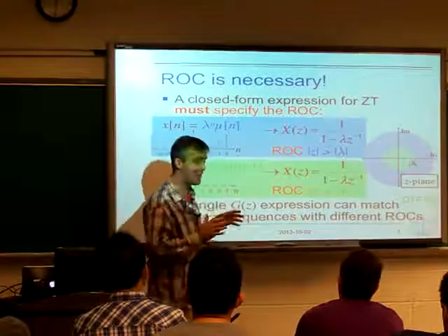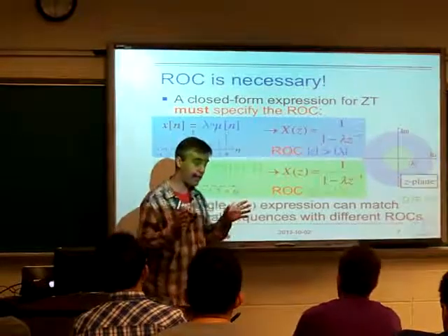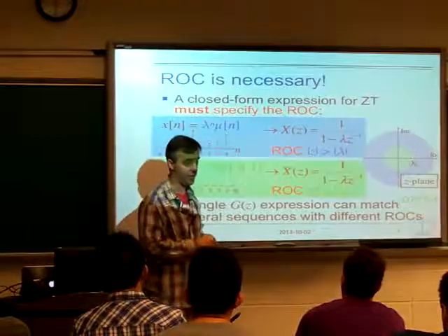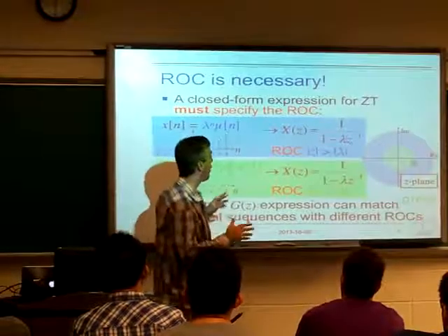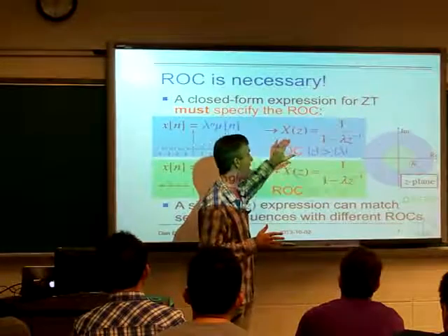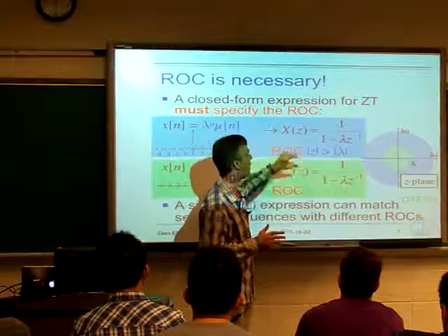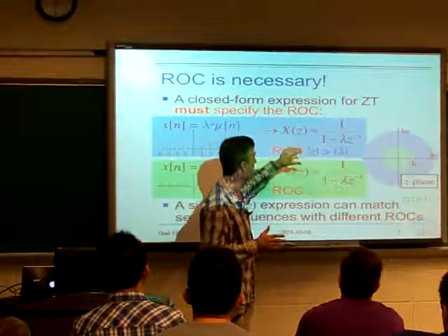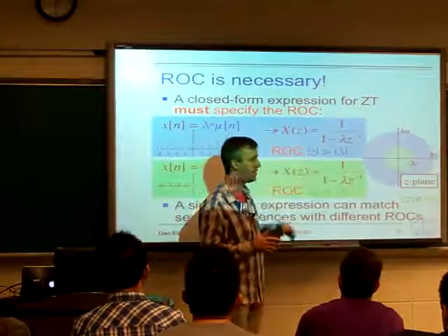The z transforms are completely different because the z transform completely defines a sequence. These sequences are completely different. But the way we handle z transforms, in terms of these closed form expressions, just happens to work out the same. And the reason that doesn't mean the sequence is the same is because they're applying to different regions.